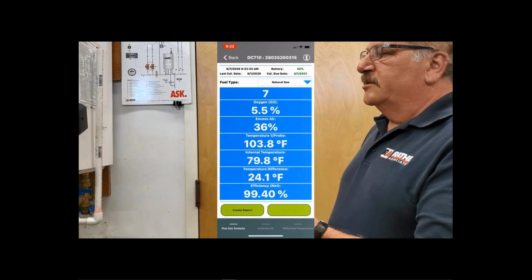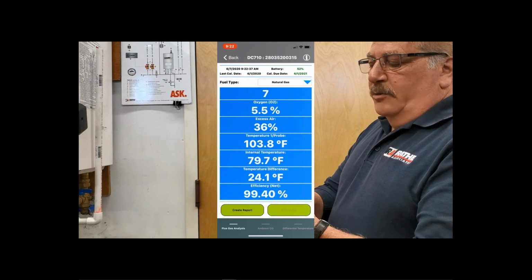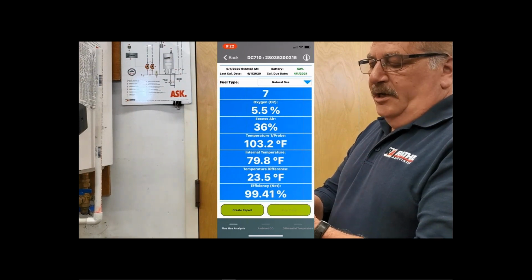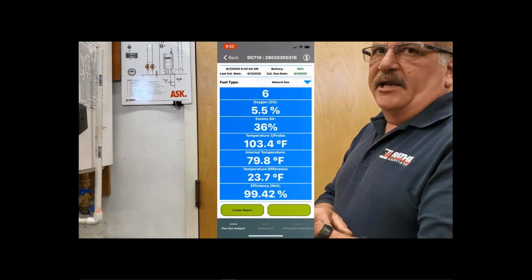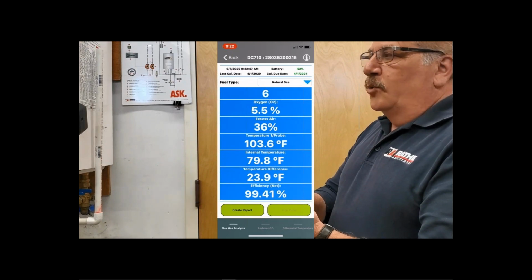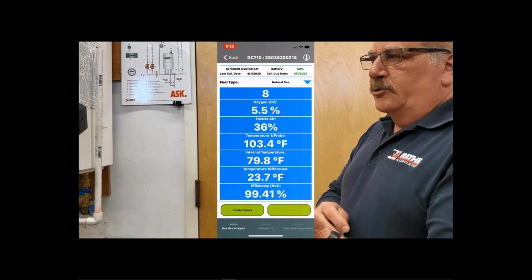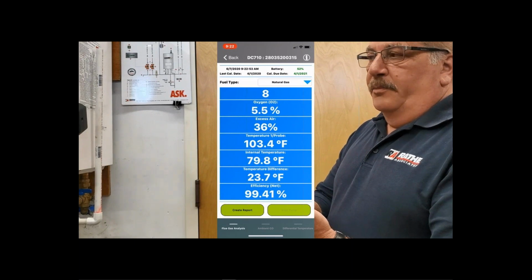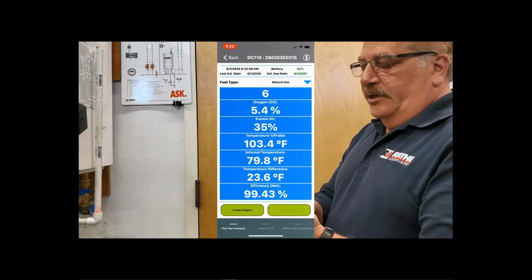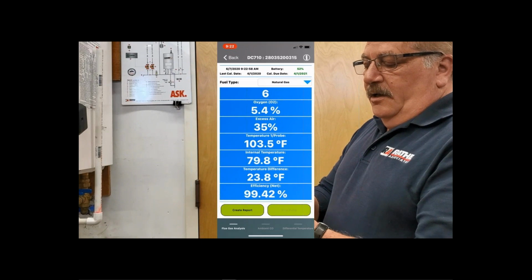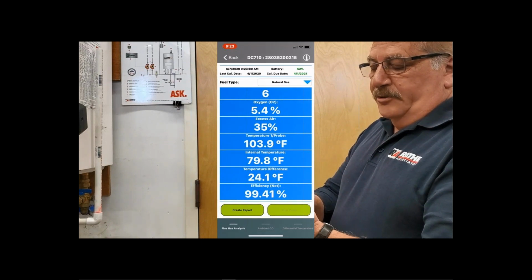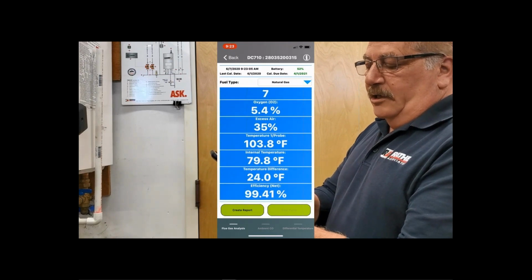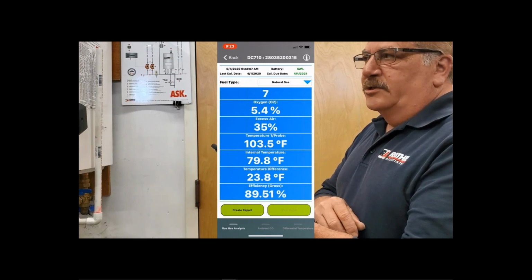Excess air, also in the stack. Temperature probe 1, since we only have one probe hooked up, shows us what the stack temperature is. The internal temperature also means ambient air temperature. If you wanted to, on the TPI device, you can hook up any K-type thermocouple to probe number 2. That would be port number 2 in the device. Moving further on, you see the temperature difference and then a net efficiency, or if you click on it, you'll see that change to a gross efficiency.